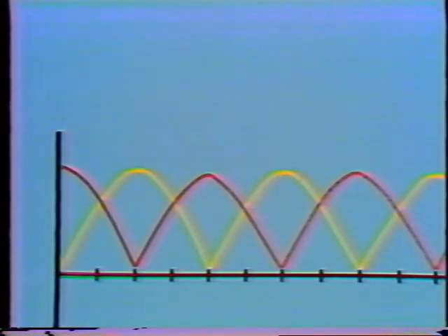As the loops rotate, one loop is always 90 degrees behind the other. So when the voltage coming off one loop is decreasing, the voltage coming off the other loop is increasing. And the brushes are always in contact with the segments of the loop that have the greatest induced voltage. As the voltage in one loop drops below the voltage in the other loop, the brushes pass from the commutator segments of the loop with the decreasing voltage to the segments of the loop with the increasing voltage.